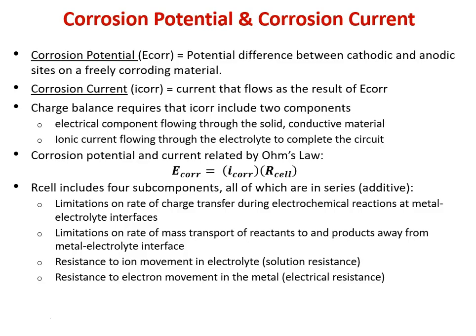We can have electrons flow from an anodic site to a cathodic site, as opposed to chemical reactions where you still have charge transferring, but it all has to be in the same place. We can have separation of anodic and cathodic, or oxidation and reduction, sites. And that's one of the reasons why metals corrode electrochemically.